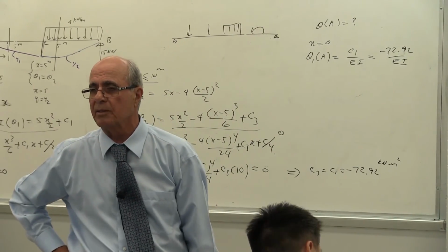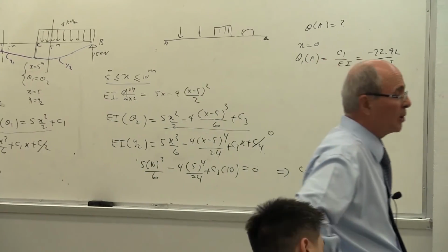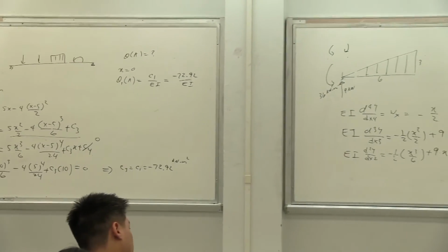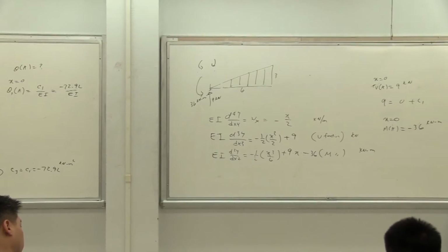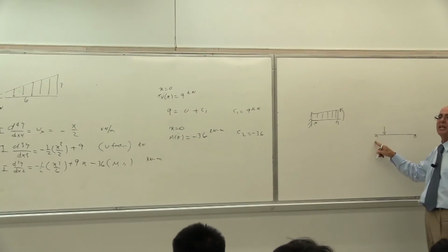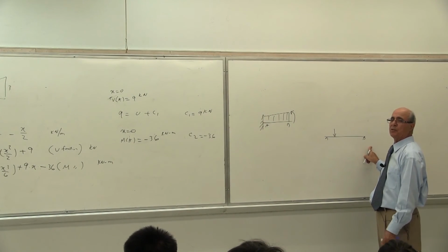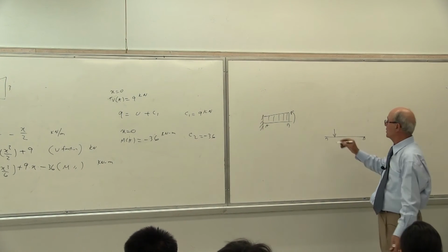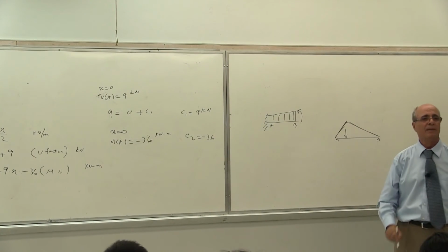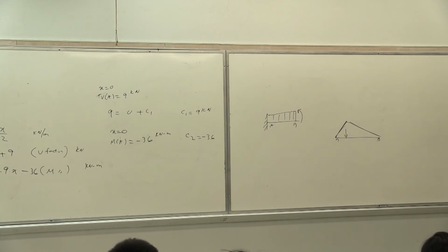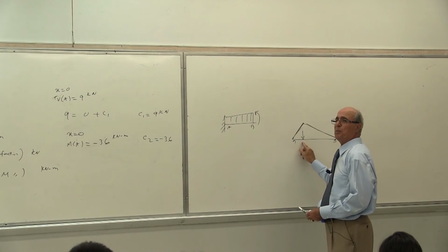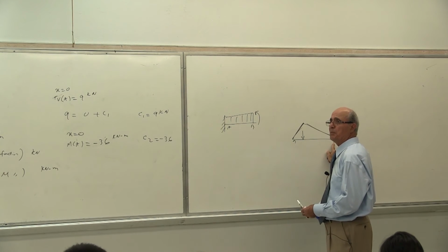Is that correct or not? So please be careful. Couple of your homework does not require like that. There is another homework which is symmetrical. So if there is one homework like that, that one you have to do it in 2 parts, AB and BC. You draw your shaft, you know what the moment is. The moment looks something like that, yes? This function is different from that function. Everybody understand what I'm saying? That one has to be integrated between A to B, and then integrated between B to C.